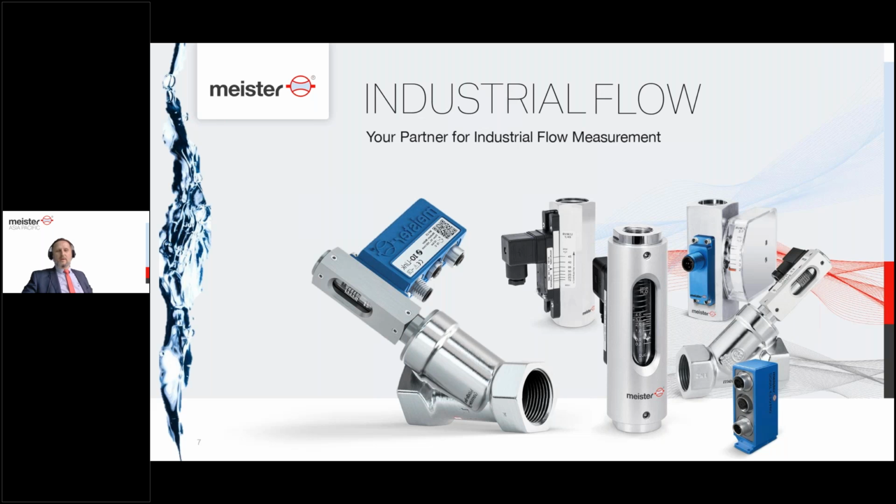In this final picture already, I want to give you a quick look into the various types of variable area flow meters that Meister has on offer. We see here flow meters with a glass tube. We see flow meters more in the back with an attached external display, which is with magnets attached to the float inside. So it still does not require a power supply.